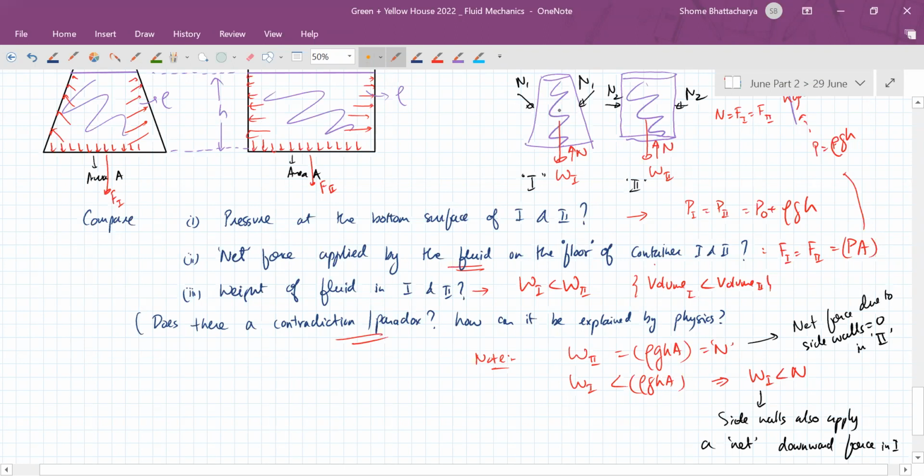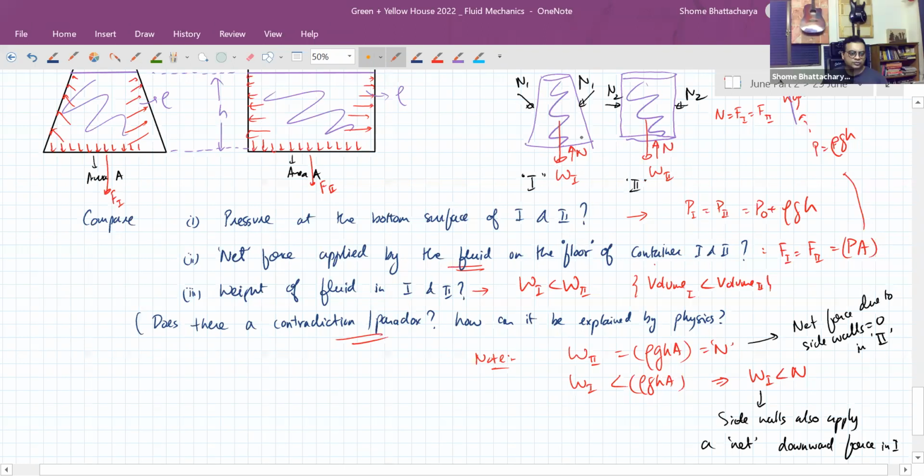So this is the free body diagram of the liquid. Okay, so that's why the direction of the force with the walls is the reaction to this. The liquid is applying downward force, so the wall applies and the floor applies upward force. The liquid is applying sideways force like this on the wall. So the wall applies equal and opposite force like this into it.